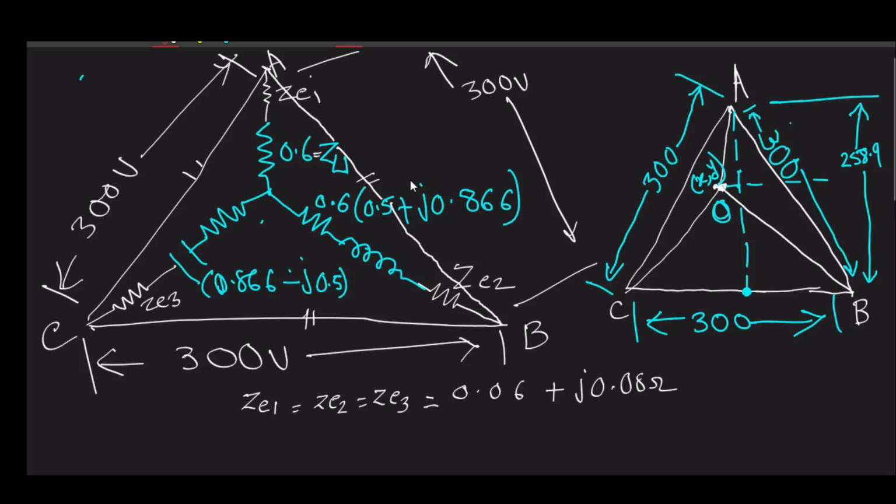that the voltage between two phases, either AB or BC or CA, is obliged to maintain 300 volt because the primary line voltage is constant. However, phase voltage can vary. There is no such bound on the phase voltage, because remember the primary side is being fed by a source that is trying to maintain a constant line voltage. That is not concerned about how you will distribute your per phase voltages, right? So phase voltages may vary even in the primary side also.